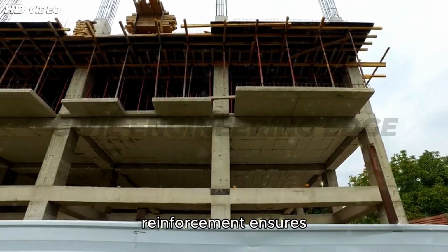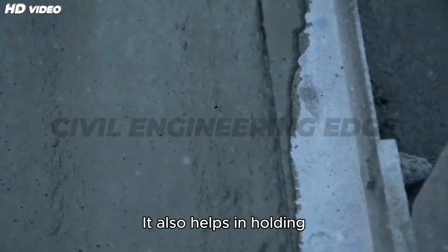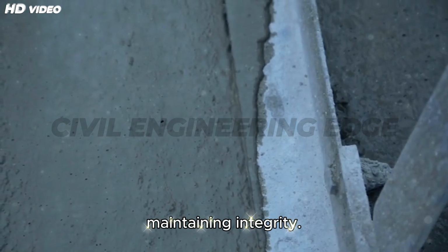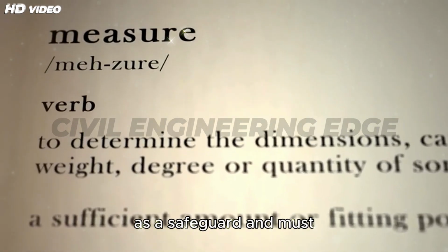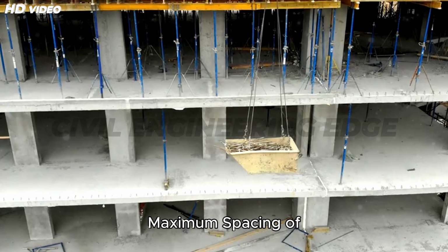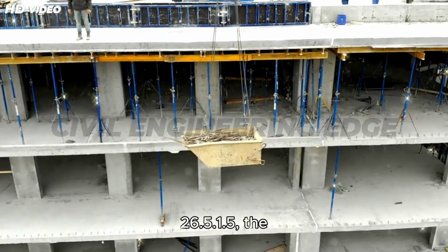Providing minimum reinforcement ensures that the beam doesn't fail suddenly and brittly under unexpected loads. It also helps in holding the concrete together after cracking, maintaining integrity. Therefore, even if shear demand is low, this reinforcement acts as a safeguard and must not be ignored in beam design.